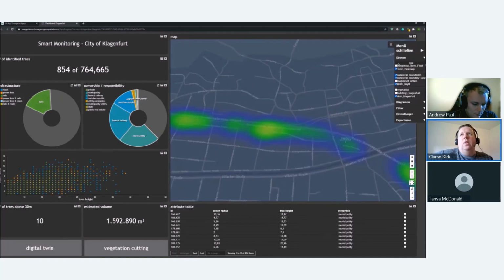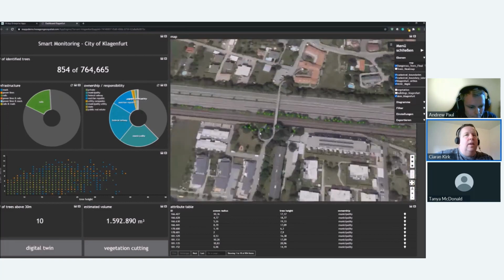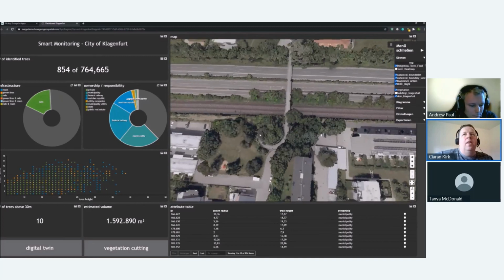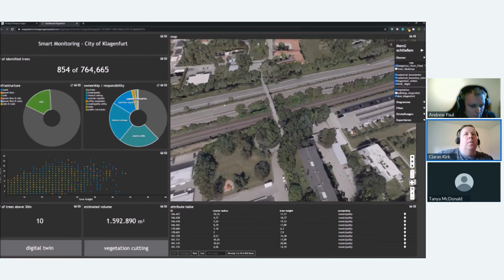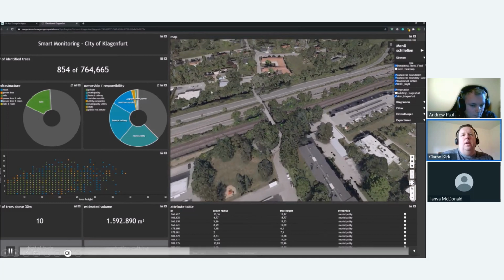So in this case, looking at the data as trees, being able to visualize the green areas here are where the trees are overlapping the utility network. And then as you can see there, you can see clearly where those trees are from the imagery, but also being able to auto-generate that from the model, from the system, and then create work and create jobs out of it, which is really useful.